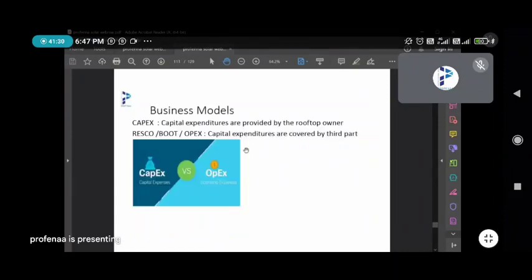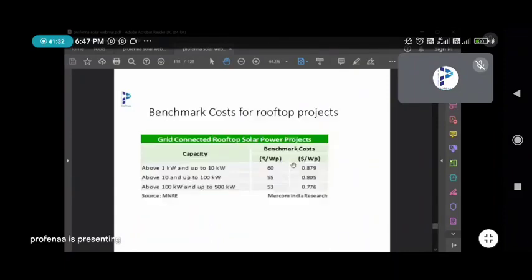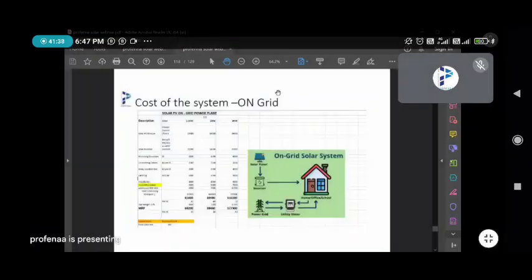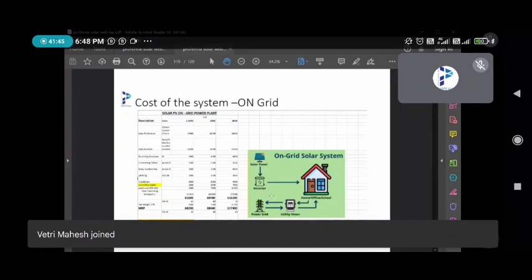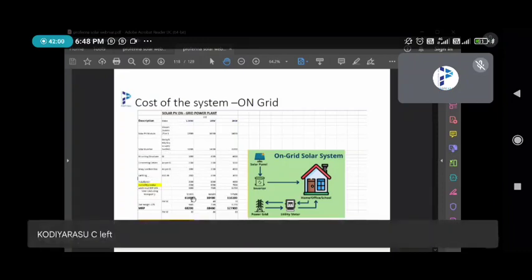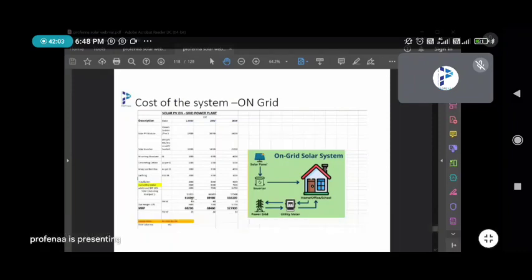So these are the financial details, how it will come. There are two models. So for the 1 kilowatt system, how much it will take. Finance based on this, here I have calculated. I already said there is a 1 kilowatt system, 50,000 rupees. How is it segregated? See, there is the panel, 27,000; there is the inverter, 10,000; mounting structure, 3,000 rupees; connecting cable, that is ACDB, DCDB, 2,000 to 3,000 rupees; earthing and lightning arrestor, it will cost 3,000 rupees. So totally the system will come to 55,000 rupees.